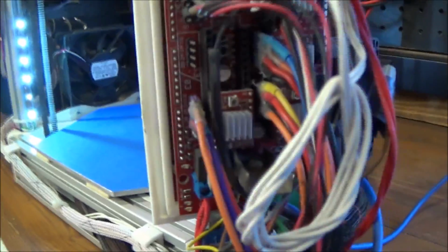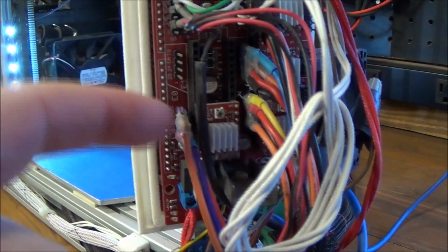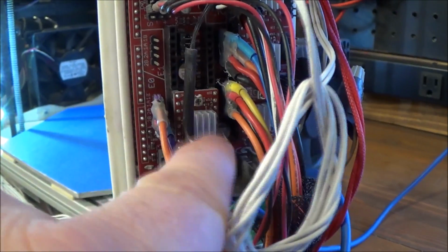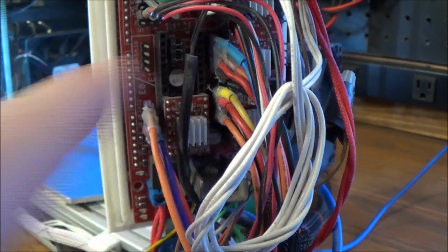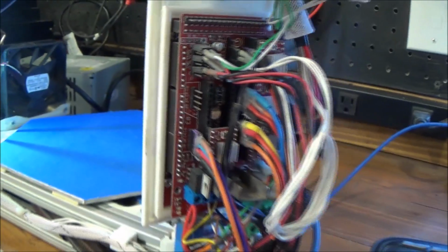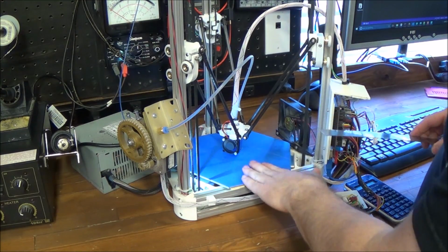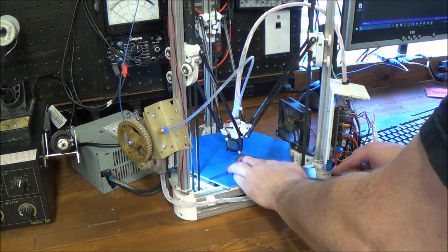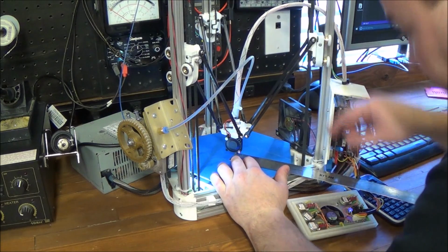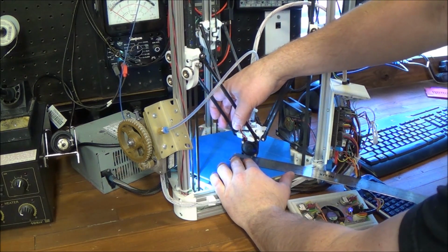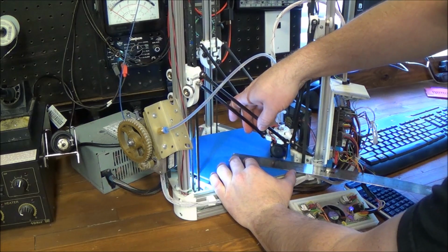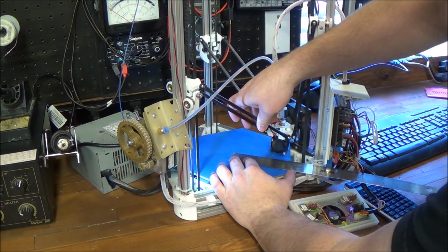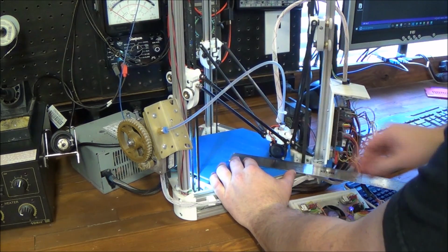And then the other thing we need to know, we're using these Pololu stepper motor drivers, and I've got all these jumper pins installed underneath them, which means I'm going to use the maximum number of steps, which is 16. The printable radius variable, bring this down in the middle, and then let's measure how far we think this can print without hitting something. So we're going to go to about 90 millimeters. That's about as much room as I can get here.